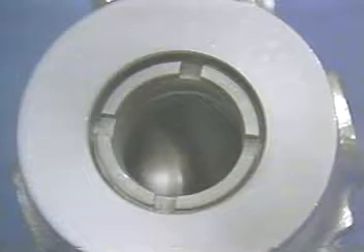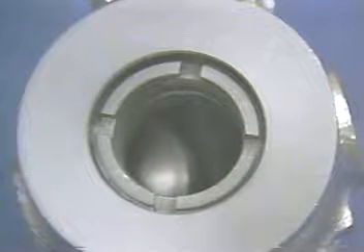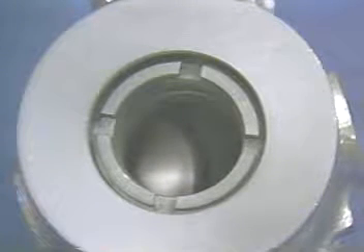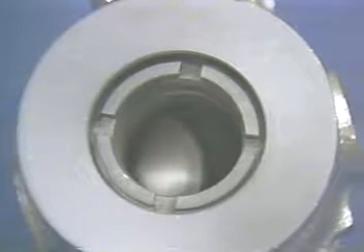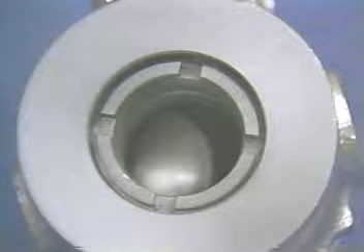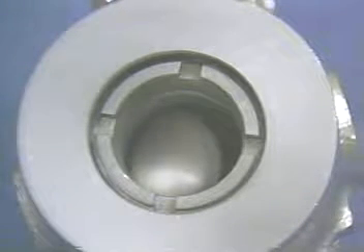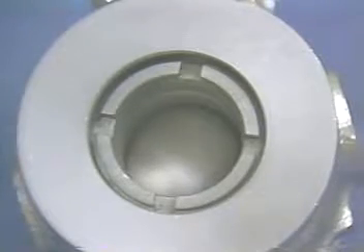These valves are closed by rotating a plug that has a port in it. The plug can be cylindrical, as shown here, conical, or spherical in nature. Additionally, the port may be characterized to provide a desired flow characteristic. This eccentrically rotating spherical plug valve provides for a modified linear flow characteristic, as well as a tight shutoff and easy operation. Valves such as these are widely used for handling viscous liquids and slurries.